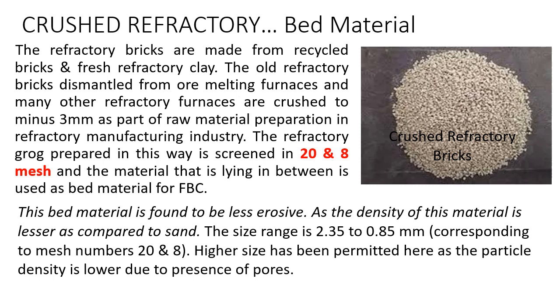This bed material is found to be less erosive as the density of the material is lesser as compared to the sand. The size range is from 2.35 to 0.85 mm, corresponding to mesh numbers 20 and 8. Higher size has been permitted here as the particle density is lower due to presence of pores.